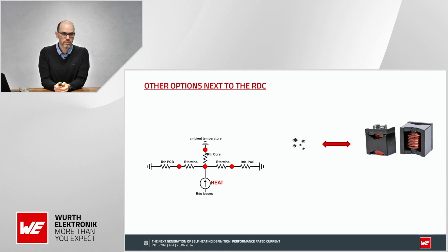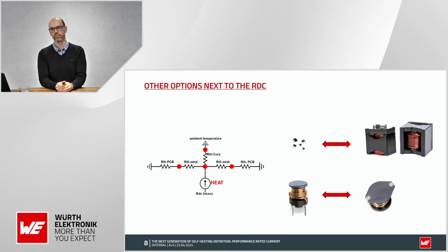What else is there? Like said, power inductors are single coil power inductors, so we have one input and one output. And for sure, all inductors are sooner or later mounted onto the PCB. And there we have two kinds of connection possibilities. The one is THT and the other is SMT. But there the things are getting interesting, because if I have a pretty big area where I can connect my part onto the PCB, and then I can put a pretty big copper plane on that connection area, then things can get interesting.